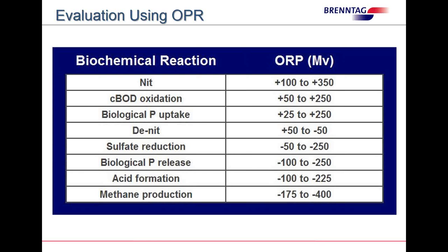If we have a number reading in our oxidation ditch, and let's say we set the ORP meter and start testing the water at, let's say, plus 135, and we bring that water in and we do an ammonia test on it, and the ammonia is 0, that's your number from then on. So we could just set our meter at 135 and increase or decrease air supply based on that number, and we would know we had it.